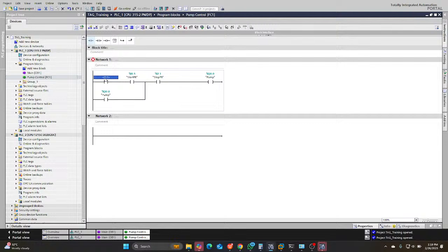This is just a simple program. Let's use I3.6. Since we have manual and auto mode, we must be able to select if we want to do manual and auto mode. Okay, so I rename this as selector manual/auto. It's off is on auto. If it's on is on manual. So that's why I'm doing it this way.